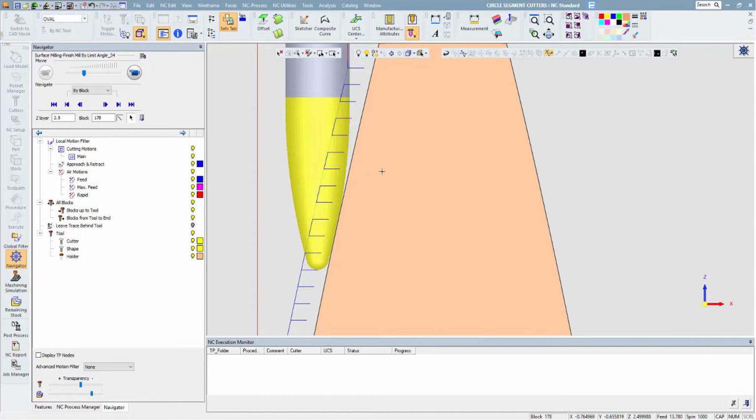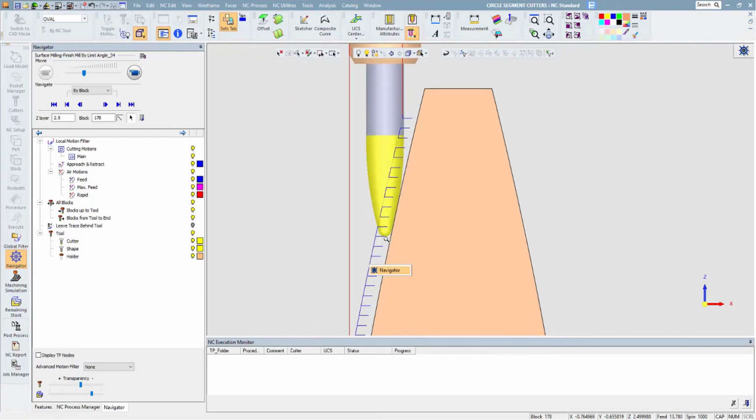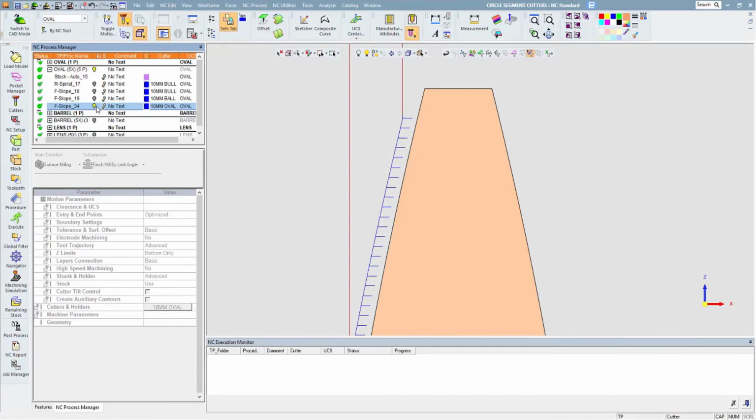Now, in 5-axis, we can do more tilting to keep it better engaged, and that can make an even bigger difference, and it's what most applications it's going to get used for. But you can see here in this 3-axis application, you're cutting down a tall standing rib, something like that. This can do a lot better job finishing down quickly versus traditional tooling. So you'll see an increase in the surface finish as well, typically.